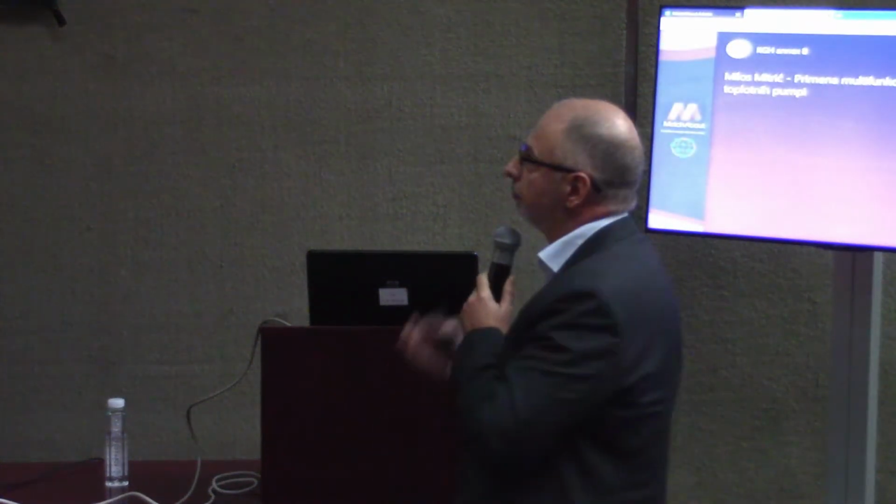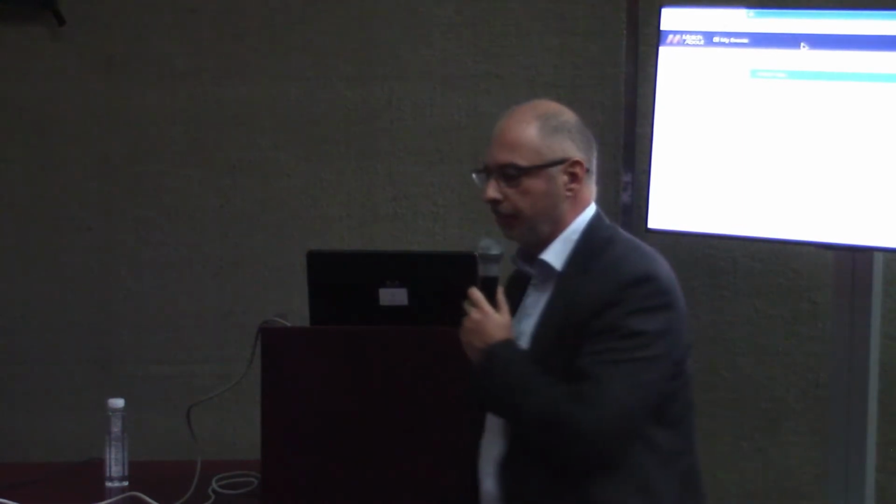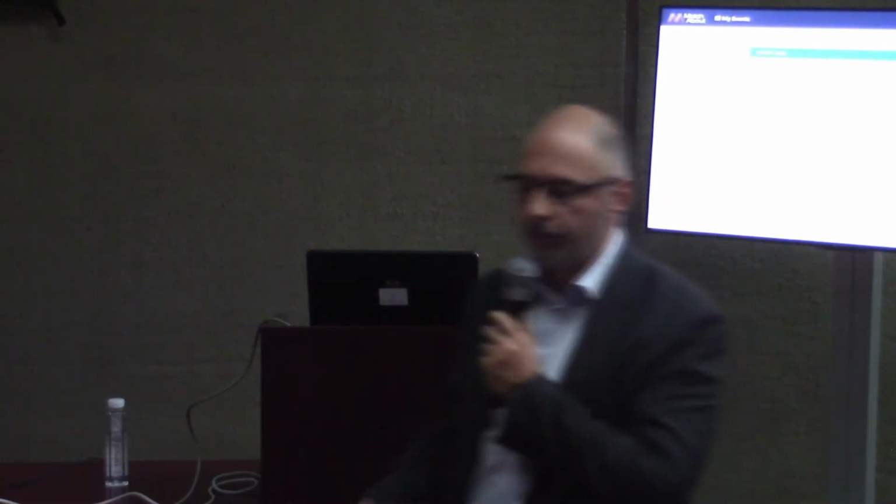What is small? This is a big question. In this paper, we look at systems between 40 and 70 kilowatts because they fit this ejector, which we will talk about later. So, commercial refrigeration systems. What is a commercial refrigeration system? It is a system with multiple evaporators, so 10 plus evaporators. It's not a single evaporator like it is in the picture.